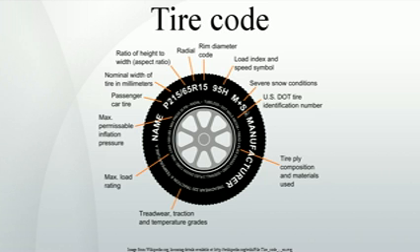If the tire diameter is not given, section widths ending in 0, for example, 7.00 or 10.50, indicate the aspect ratio is 92%, while section widths not ending in 0, for example, 7.05 or 10.55, indicate the aspect ratio is 82%. These aspect ratios often vary from today's tire manufacturer specification. Construction of the fabric of the tire.